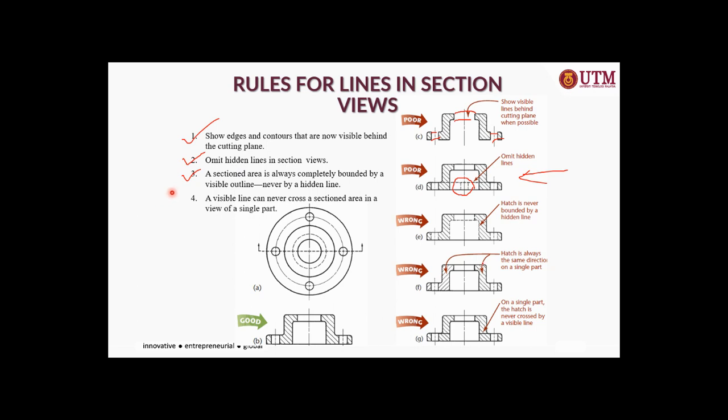And then the fourth rule is that whenever you do a hatching, make sure that the direction is always the same. Don't use another direction on the left and another direction on the right. It shouldn't be that way. It should be the same direction all over.